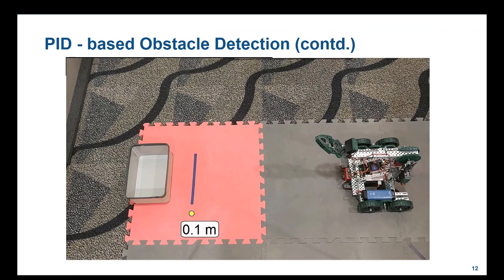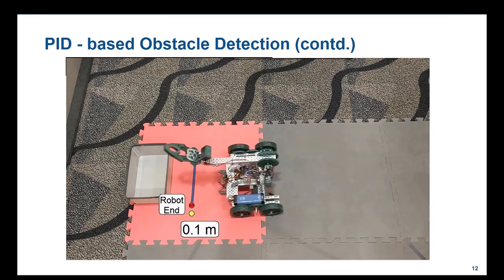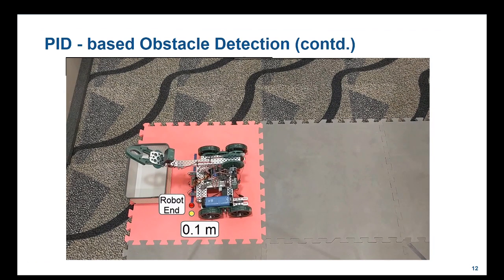In the video, we see that the robot starts fast but gets slower as it gets closer to the obstacle. We can see that it ends up closer to the desired distance to the obstacle as compared to the on-off algorithm. We can also see that the robot is not oscillating much towards the end. This is because in the real world, sometimes some of the smaller noises are damped due to either the mass of the robot or initial friction of the motor or some other reason.